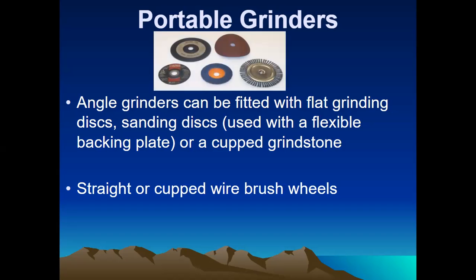So in this picture here that we see, starting on the left on the bottom, that's going to be your standard metal grinding disc. Above that, that could be an aluminum grinding disc. Now, different compositions for different discs. Aluminum is much softer and it will fill the pores on a disc and pretty much make it useless. So these aluminum ones are designed to self-clear better.